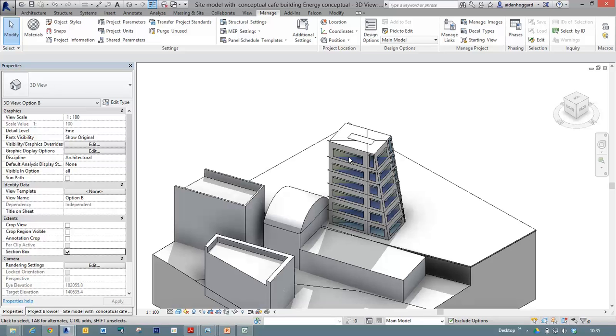I have not sat down and defined these windows like this, because in terms of early stage design, all we're really interested in is the amount of glazing, the area of glazing, is it shaded, orientation. Because what we want to do is compare these design options. So at a conceptual level, you don't want a hugely complex model. That's what we'll look at in the next session.